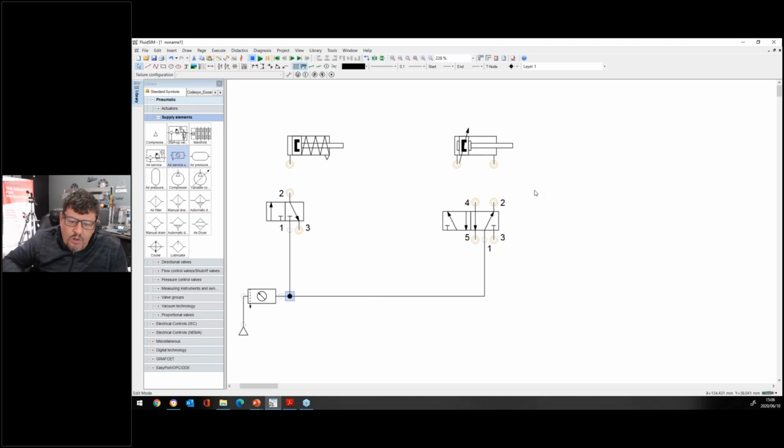Then, guys, it is important to understand this now, we need to connect our outlet ports from the valve, and like we have discussed, we have now a 3/2-way. 3/2-way means there's 1, 2, 3 ports, 2 squares, right? And my rest position, or what I refer to as my normal rest position, will be on my right hand side. That is the initial position of the spool. All right, same on your 5/2-way valve. Right, this is connecting to my double acting cylinder in front, this one to the back.